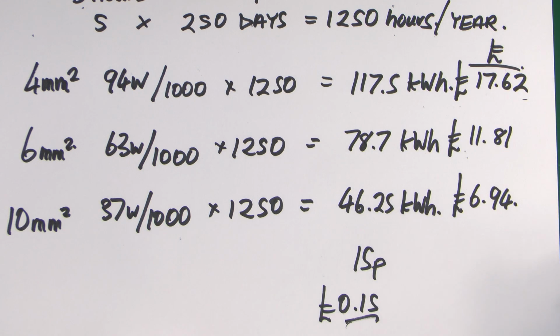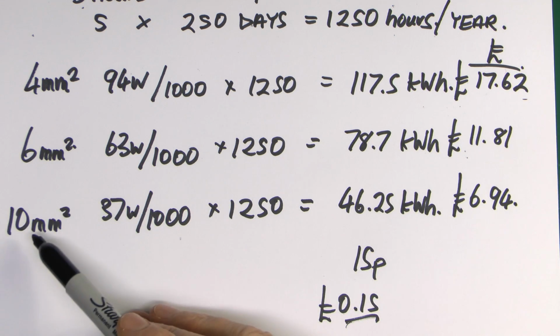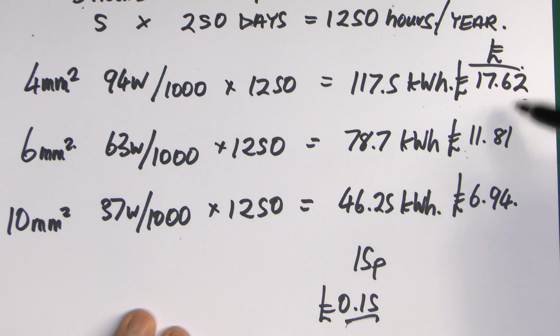Now all of these are electrically compliant, there's no particular problem there, but what we're trying to consider here is whether it's worthwhile paying initially for a bigger size of cable, because it might save the homeowner or whatever some money in the longer term. So